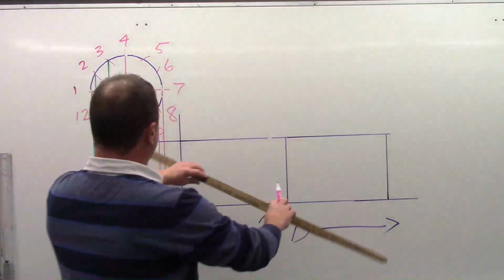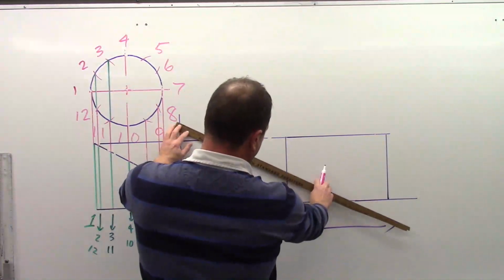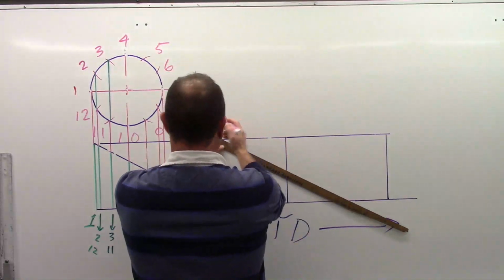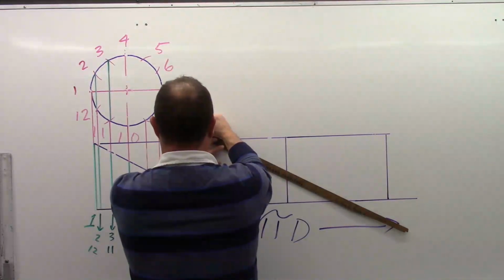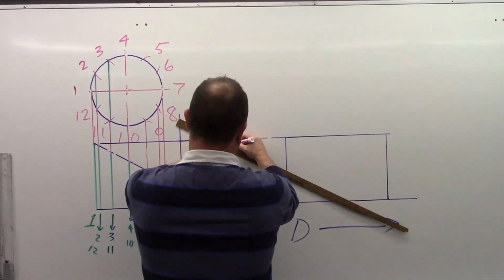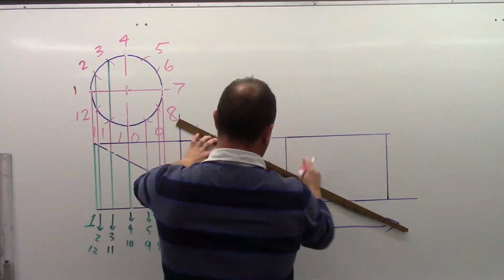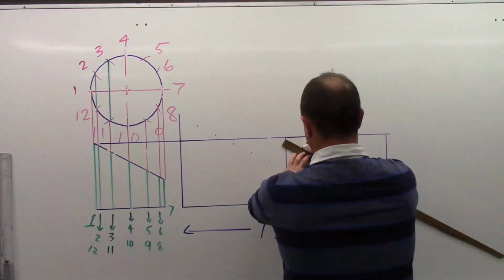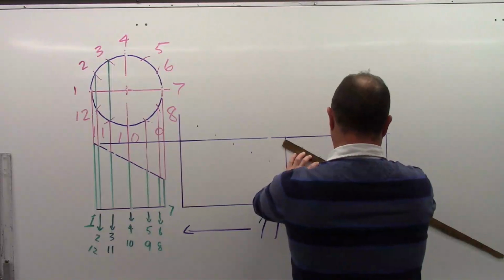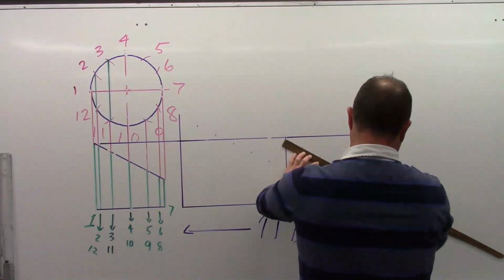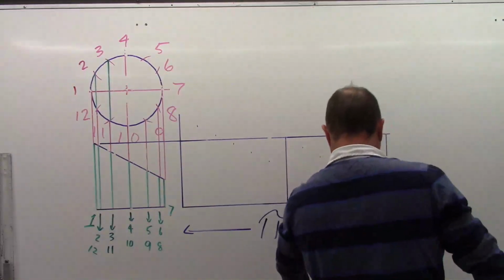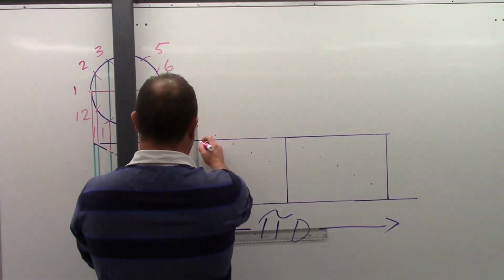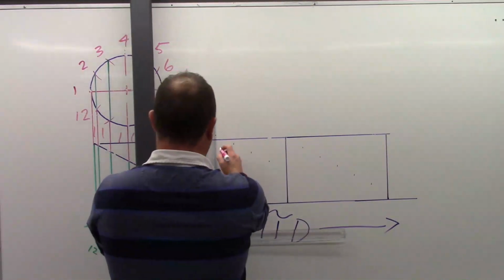I'm going to use my ruler on a diagonal, and I'm going to find there's a good one there. In my case, I've marked 0 and 18 inches, and I'm going to mark every 3 inches. That will give me 6 equal divisions each side of center. If it's too long to do a 12, which in most cases when we're in the drafting room we have a small 12-inch ruler, so we can't really do much with it unless it's a very small part. And I've squared these all down.